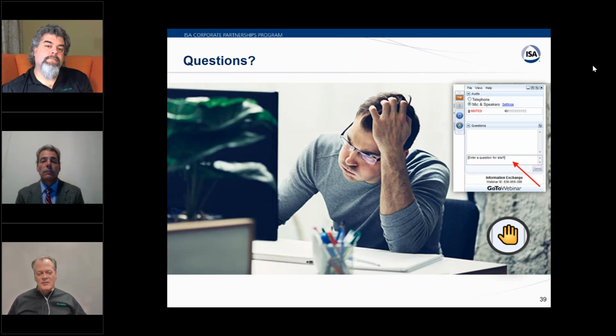So, to add to what Ned is describing, if you say, for example, SIL2 is your target, and I've had this lots of times when I'm brought in to do the verification calculations, they design stuff with non-redundant sensors and final elements. They're assuming yearly testing, and all I do in my modeling is show, sorry, you don't meet your SIL2 target. Well, you need to change something now, and you need to do this analysis early in the design before you start purchasing and building stuff.